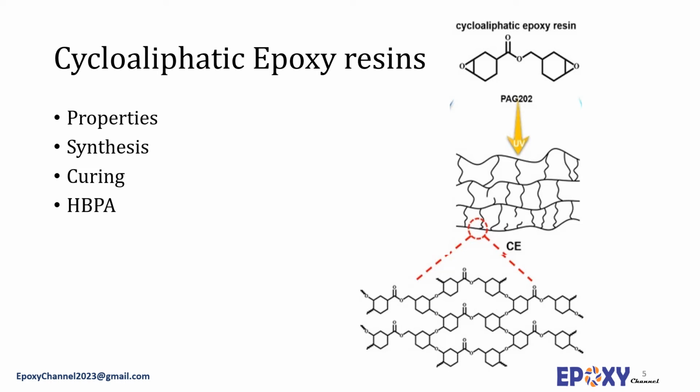Because aliphatic epoxies have a lower electron density than aromatic ones, cycloaliphatic epoxies react less readily with nucleophiles, whereas bisphenol A based epoxy resins, which have aromatic ether groups, can react. This means that the conventional nucleophilic hardeners such as amines are hardly suitable for cross-linking. Cycloaliphatic epoxies are therefore usually homopolymerized thermally or UV initiated in an electrophilic or cationic reaction.